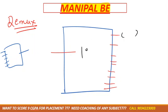So suppose it is a 1 is to 8 demultiplexer, then D0 is the input and the outputs are Y0, Y1, Y2, Y3 and so on up to Y7. Correct? Here, similarly, you have to draw the truth table for the demultiplexer for 1 is to 8.